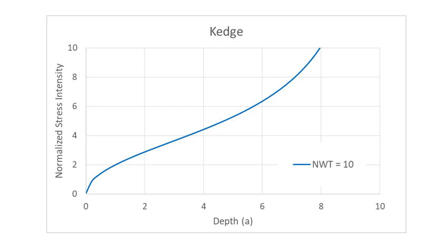Now you see from the shape of this curve that when the cracks are shallow, on the left side of the curve, the square root of pi times crack depth term dominates. And so we can see a fairly distinctive square root relationship there. However, as the crack gets deeper, the secant term comes into play and starts to increase that stress intensity factor up and away from the typical square root relationship. That curvature becomes quite important when we start thinking about crack stability. And I'll show you how and why.